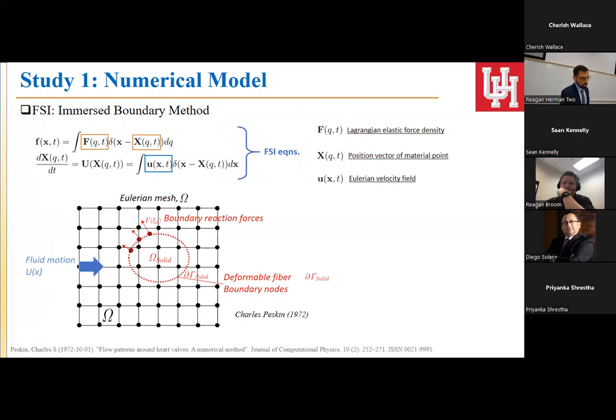Moving forward, the next step would be to actually capture the fluid structure interaction that happens here. So what would be the first step? The first step is to solve the fluid equations, right? So you can get the pressures and maybe the wall shear on your structure. The coupled Eulerian Lagrangian framework uses a particular method called the immersed boundary method, which in simple words assumes a structure and its Lagrangian mesh submerged into the fluid domain, which is Eulerian.